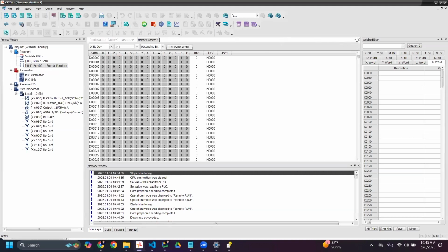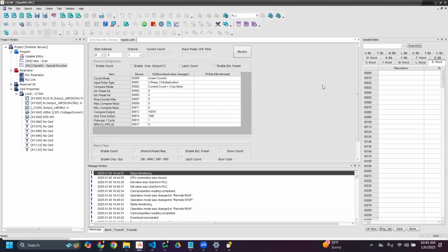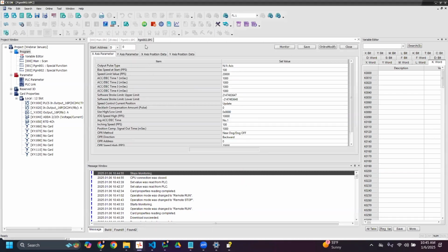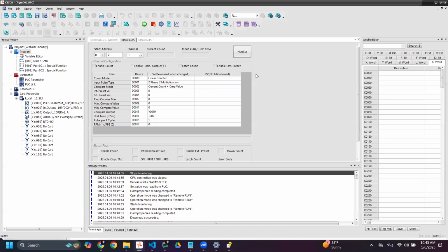While the PLC is off, that error shows up that all values are 0, which is true since, again, the PLC is off rather than the latch data. Positioning, I'll include as well. Some important information is the start address of each special program might begin at a certain data register set, and each special program can take a certain amount of words in their memory to function.